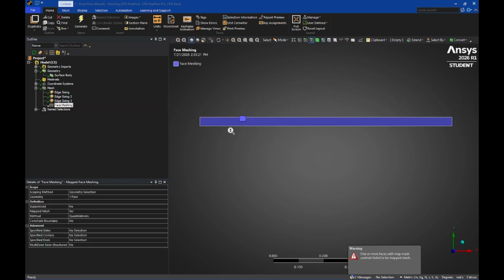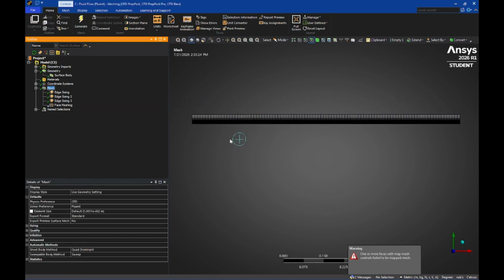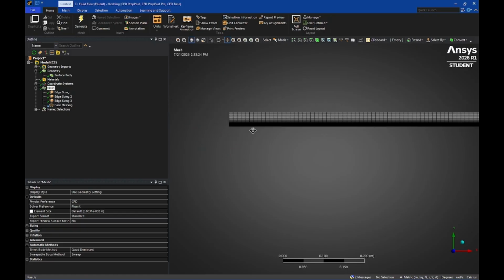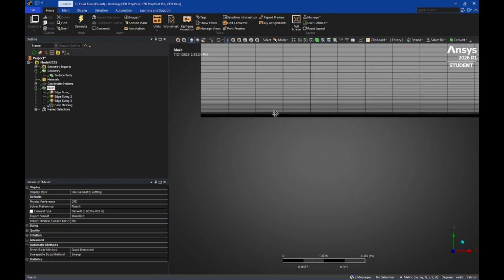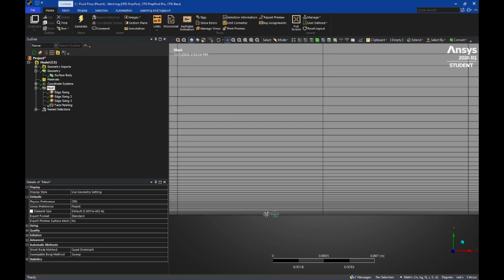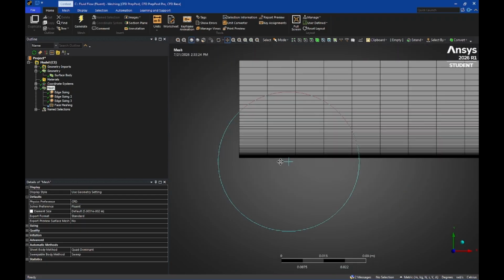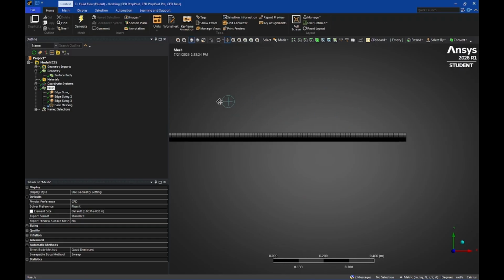And after it finishes, if you click mesh, you should see that it's nice and uniform, but most importantly, the bottom part of it has a very fine mesh. If you zoom in, you'll see that as it gets to the bottom, the mesh is very fine. Might be worth making the top and bottom plates spacing for the sizing.